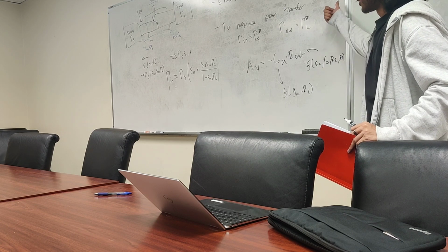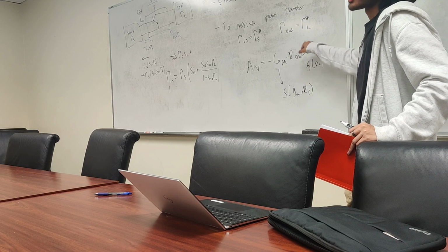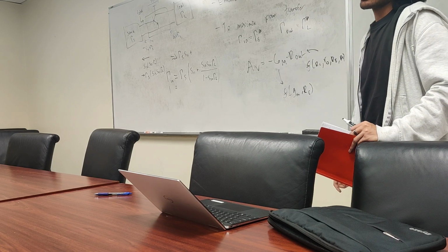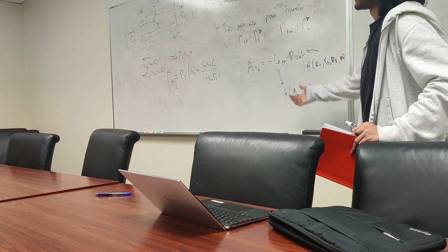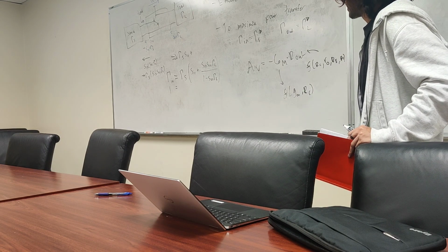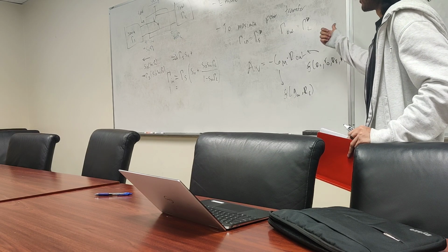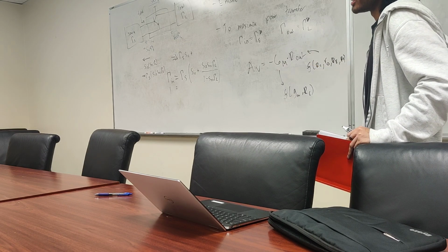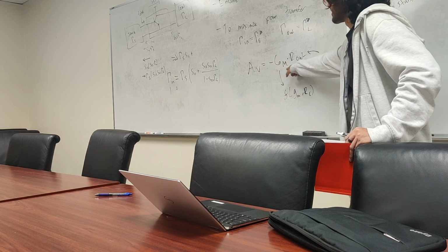RC goes up, R out goes up, RC goes up, big GM goes down, these two kind of cancel out and their voltage gain stays the same. We didn't see that before, but now because we take into account S parameters and the reflections, we can see that we can't just simply make one of these parameters super large. There's going to be some interplay between them, because we can't just assume these to be independent functions.